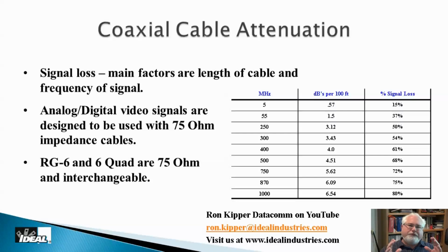Okay. The second factor is the frequency of the signal, and we are working at very high frequency stuff. And a good analogy for you guys is sound traveling through air. Very similar to electrons traveling on a cable. If you're stopped at the red light at night and you hear the guy's stereo behind just being blasted, what do you hear? You hear, of course, the boom, boom, boom. You don't hear the high-end portion of that music, and that's because it dissipates so much faster. So the higher the frequency, the more loss there is associated with this.